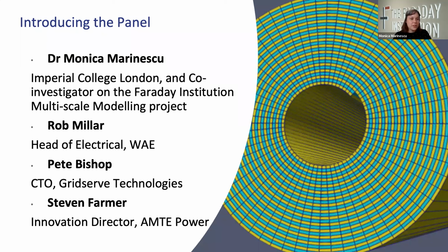So for the sake of these models being usable in industry, a focus on inputs and outputs that are measurable and standardized, and on the test procedures for obtaining those values, is very important, because we know that anything on the test rig, its thermal boundary conditions, affects the measurement you get. And so if what you're building is a pack with bottom cooling, then probably experiments from a thermal chamber are not giving you the right answers.